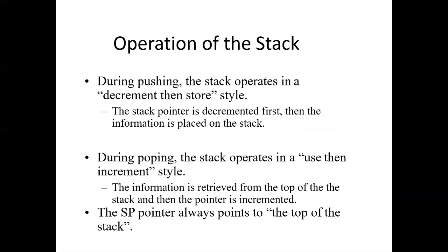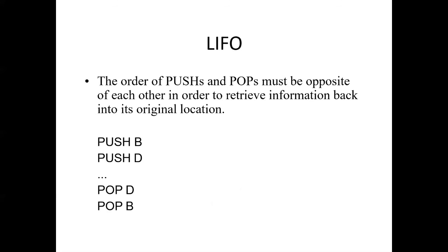Operation of the stack. During pushing, the stack operates in a decrement then store style. The stack pointer is decremented first, then the information is placed on the stack. During popping, the stack operates in a use then increment style. The information is retrieved from the top of the stack and then the pointer is incremented. The SP pointer always points to the top of the stack.